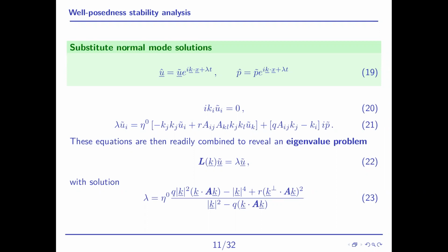Okay, so that was quite straightforward. All the gradient terms, all the derivatives, are just bringing down different wave numbers. So where I had a d by dj, I've now got a kj, etc. But the real thing to now do is combine this all. We've got at the minute three equations for three unknowns: the two velocities and the pressure. That is quite an awkward system to work with, especially split in this way.